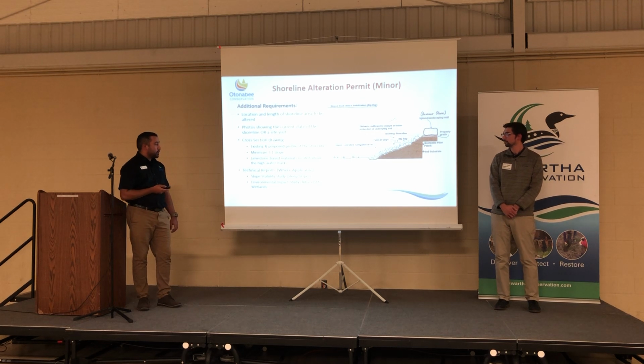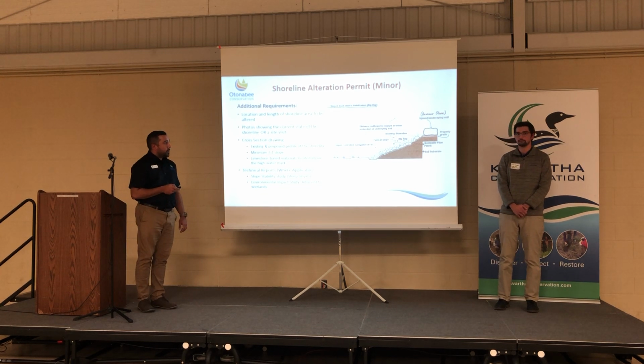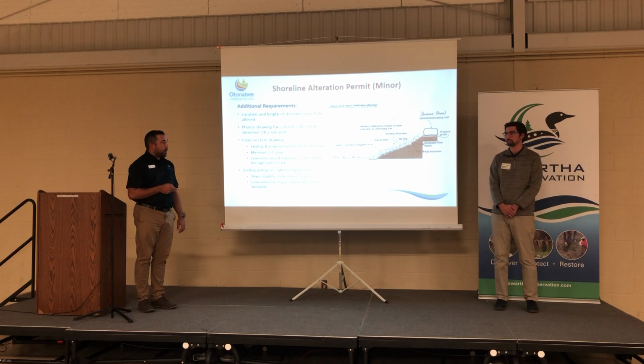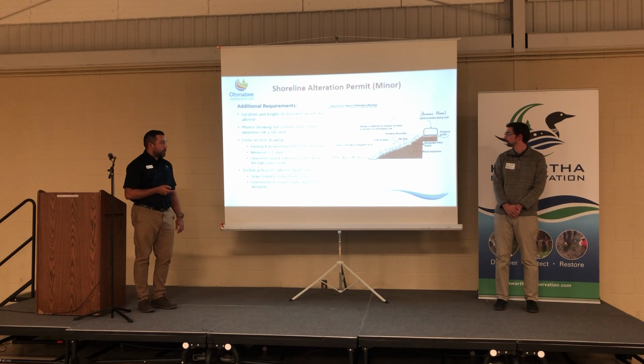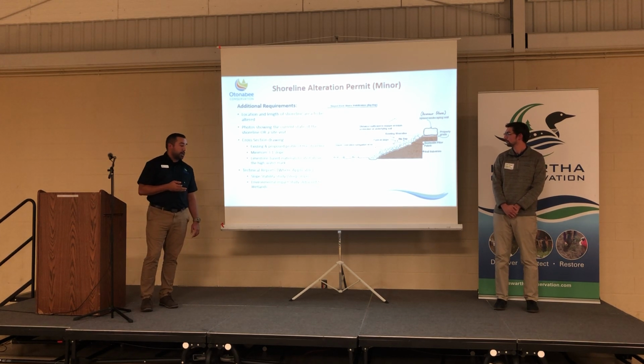There are also cases where we may ask for additional requirements like technical reports. That includes slope stability studies or environmental impact studies. A slope stability study would only be required if you're working up in the riparian zone or even the upland area and you do have a steep slope on site. We would just want to make sure that after the work is completed, that the shoreline and the slope itself will remain stable or won't cause an additional erosion hazard.